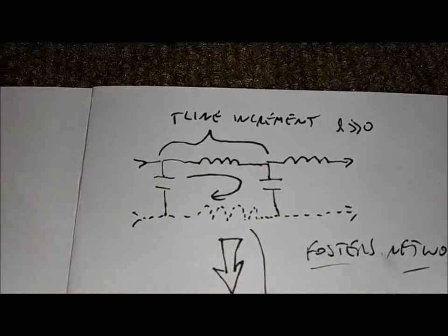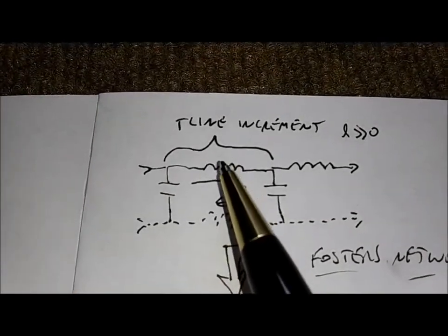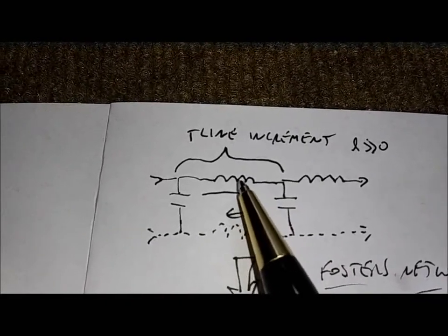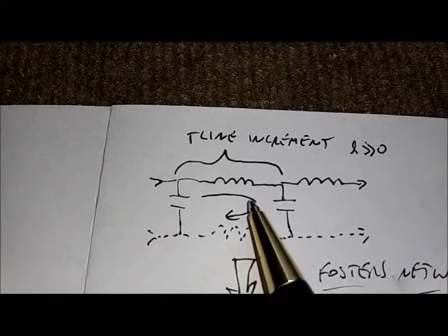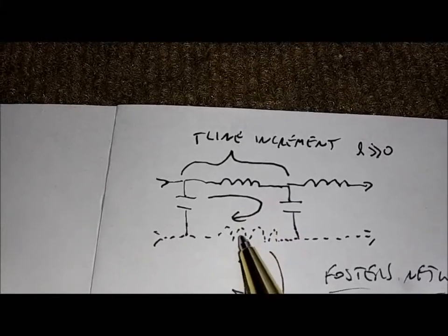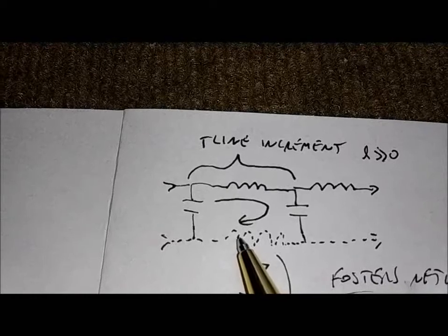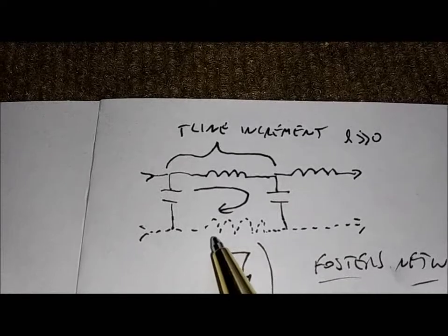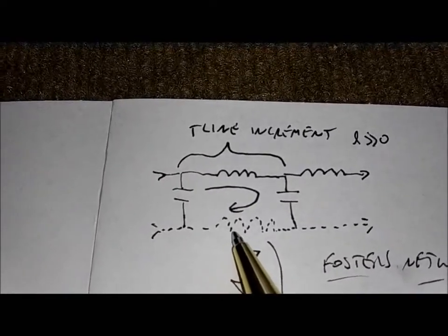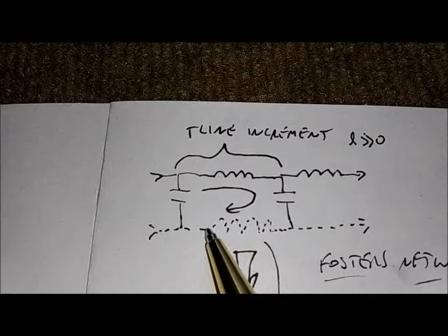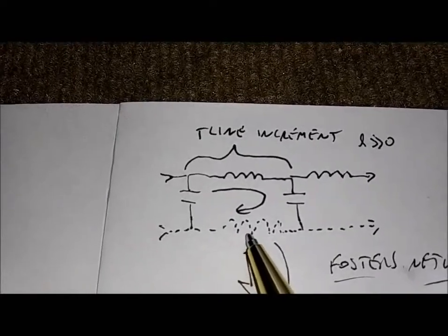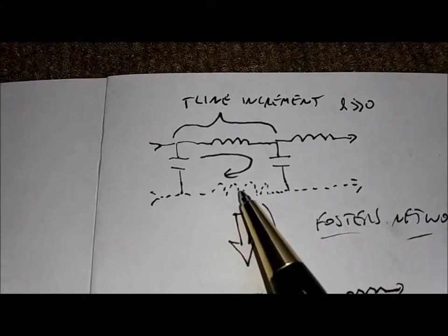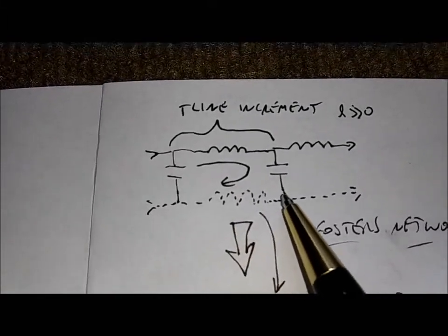Two arrows, much greater than 0. And inductance in series, that's the length of wire, an increment of length of wire in the center conductor, which is also, here's the trick, added in series with the shield inductance, which is why we never put ferrite clamps on a line, because that increases the inductance of that line in a certain area, changes the impedance of that line, and causes an impedance discontinuity and causes an SWR. Don't do that. It's a very bad idea.